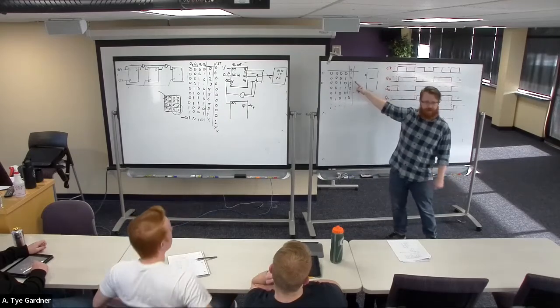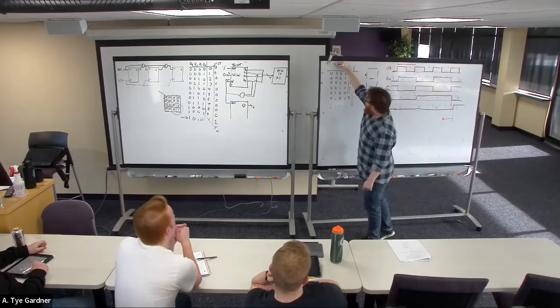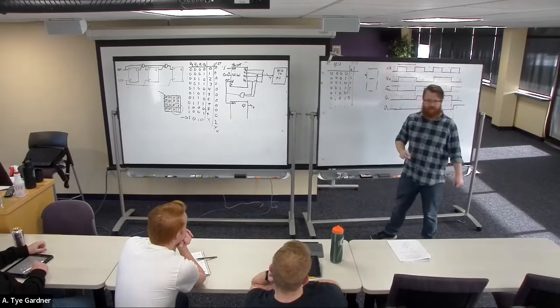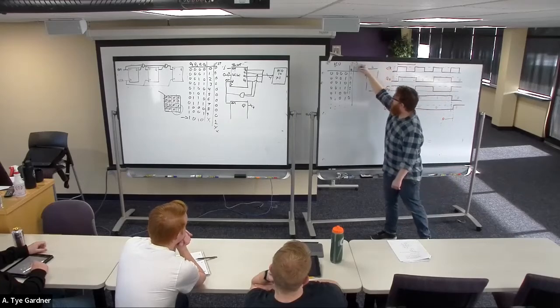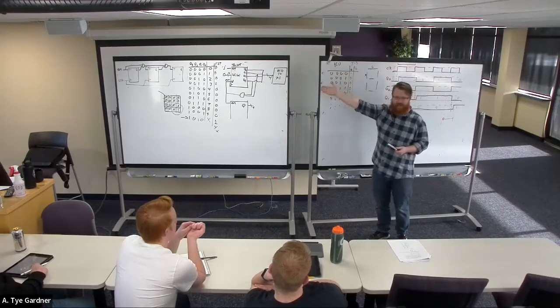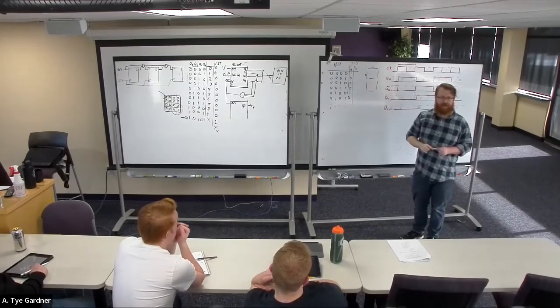This is an encoder. The circuit that results from that is it's taking my BCD and turning it into 7 segments. And then I would be like, well, this is now B. What's B? Yeah. So it's translating from binary coded decimal into human visible decimal.